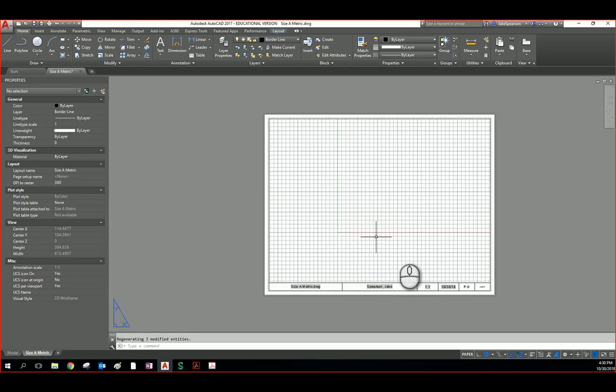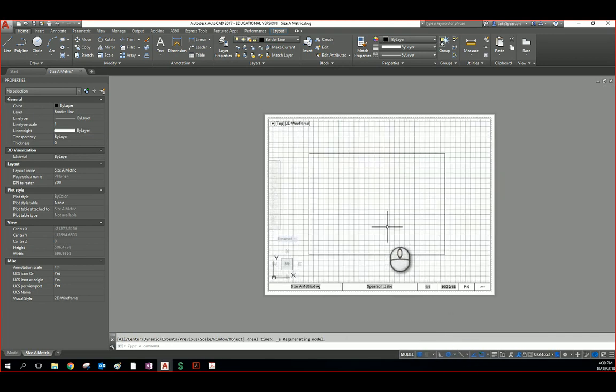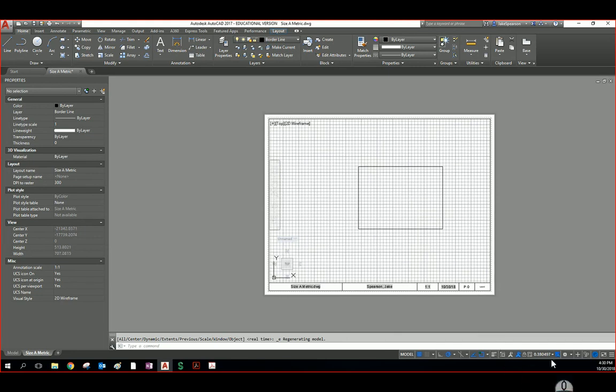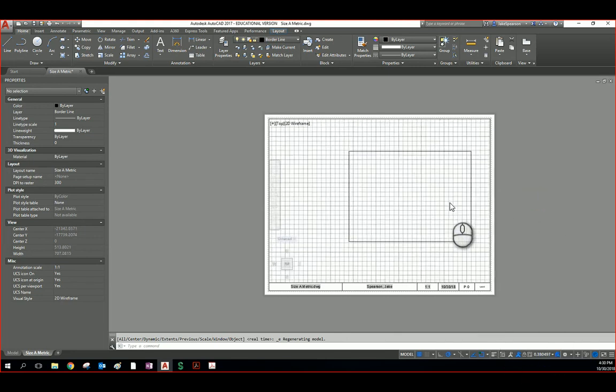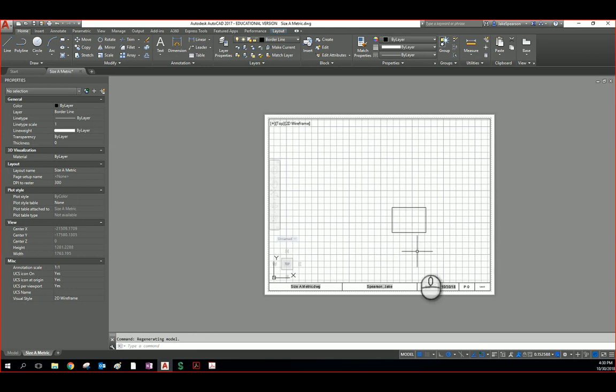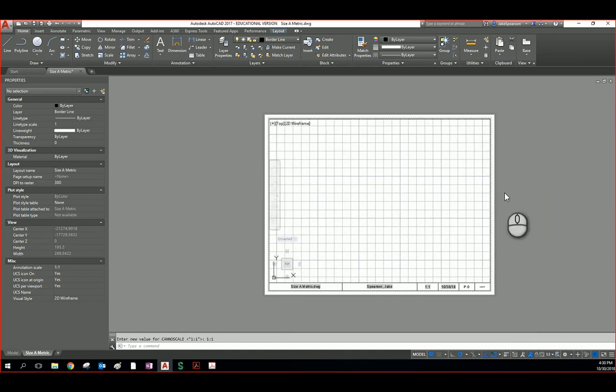So if I go back to size A, if I center click my mouse twice in model space, I can try to get this thing dead on and center. I could simply click 1-to-1 and then try to move it around to meet those corners. Or I can simply select the center mouse twice and notice how close it gets, and then just change this to a 1-to-1. And it gets exactly where I want it to go. And then I'm going to lock it.